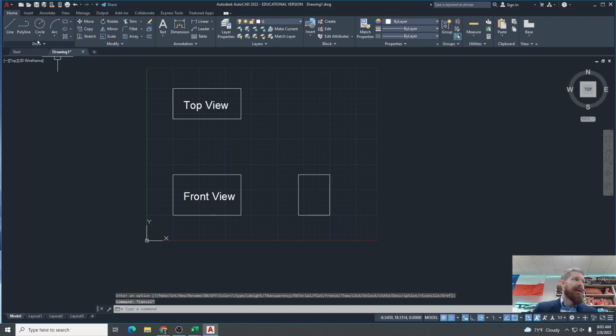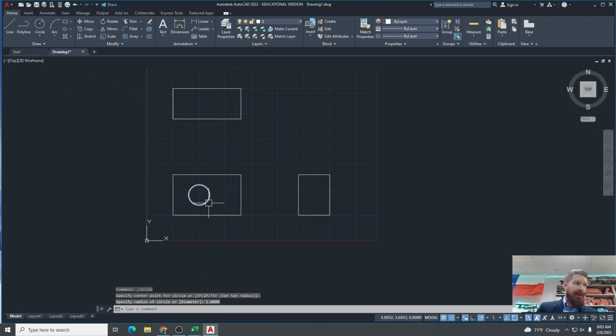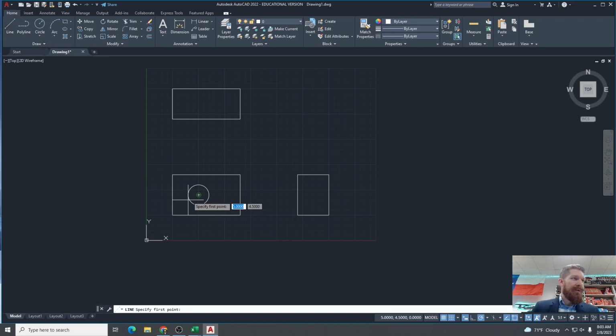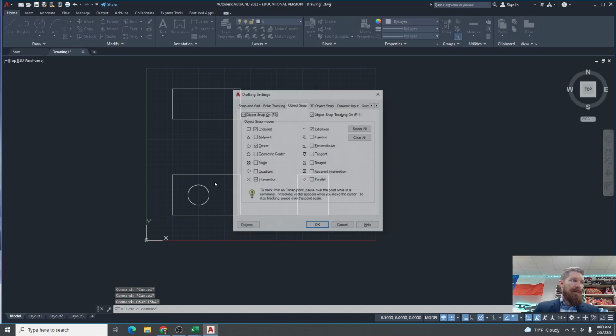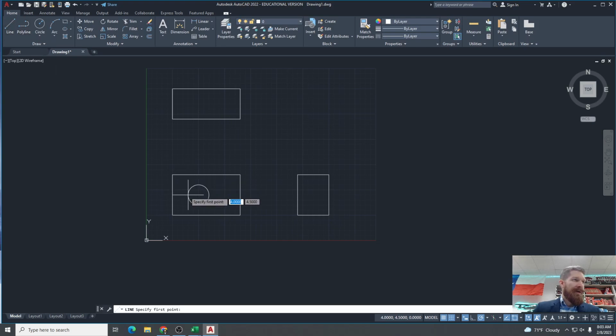How are we doing? Okay, a couple minutes. Let's say somewhere in your drawing you have a circle. So let me get rid of this text here. Let's say we have a circle here in the middle of this view, and it's a 1-inch diameter circle. What is that going to look like up here on my top view and my right view? Well, what we need to do is draw those construction lines, right? Uh-oh, I need to turn off this center point. Yeah. Here's what it's going to look like.